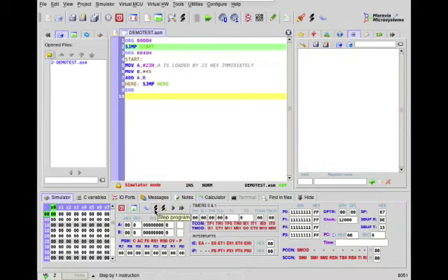So here there are actually four buttons. If we put the arrow on the first button, that is single step mode, that is step programming. The second button is step over. The third button is animate the program. If virtual hardware is there, we can use this animate button, and this is for the full run program.